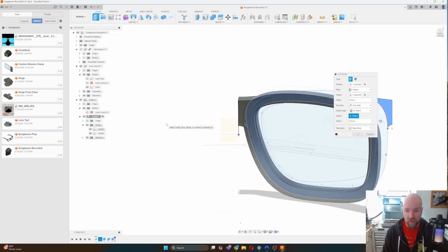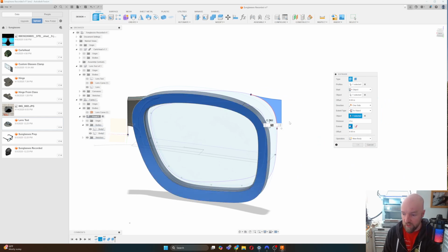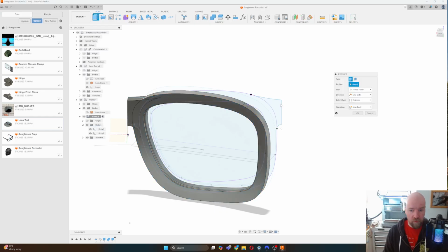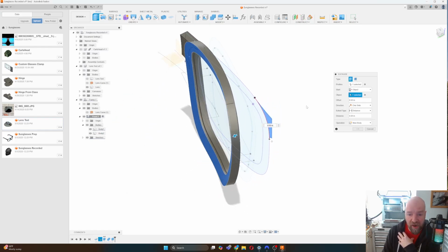And that is going to be the other side of this face. Oh, nope, doesn't want to do that. Let's extrude. Well, it needs to extrude from an object for sure. What if I just extrude it out from the back here? Nope, the extrusion profile is outside of the boundary.